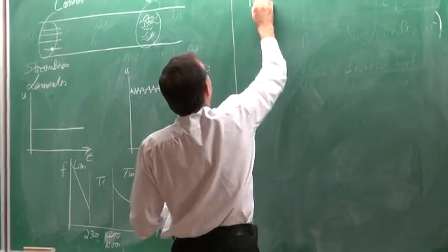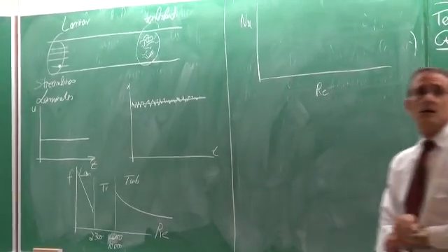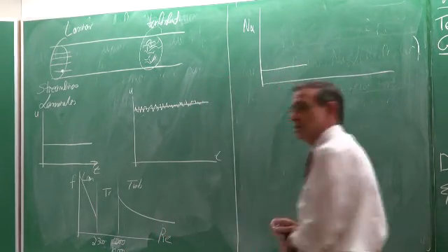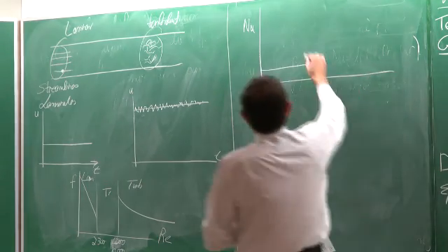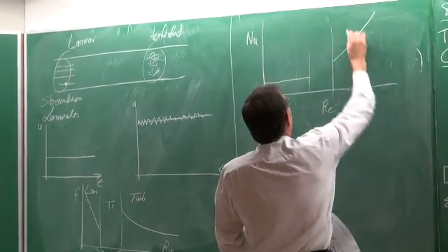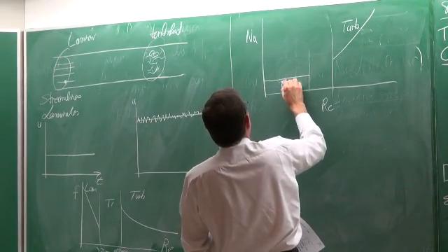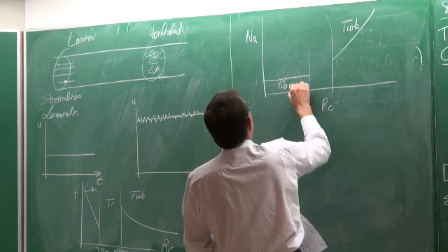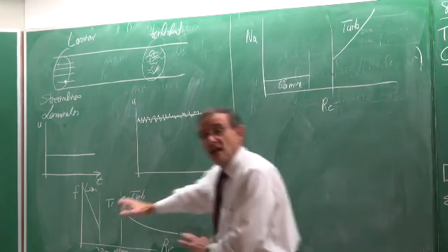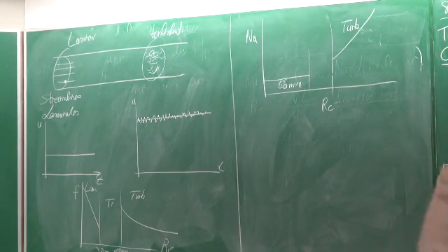If we look at the Nusselt numbers as a function of Reynolds number, then if the flow is forced convection, it should all be a constant, and I'm going to show it to you later on, up to the point where we get transition, and then from there on we will get the turbulent flow. So it would look approximately something like that. Okay, so the flow regime, as you can see, has a huge influence on the friction factor, the pressure drops, and the heat transfer rate.